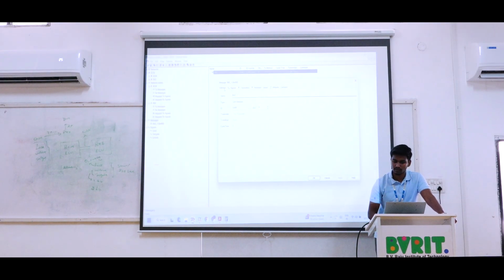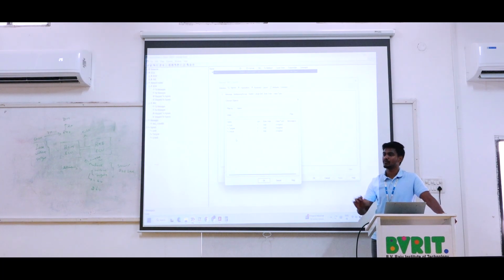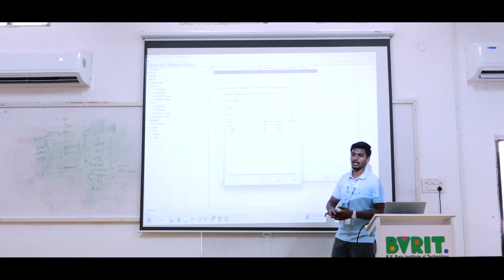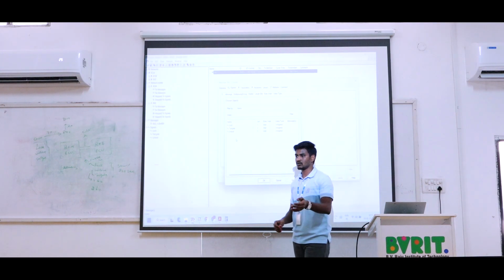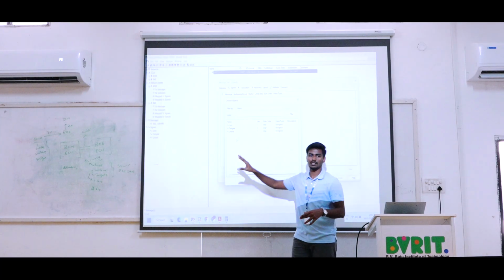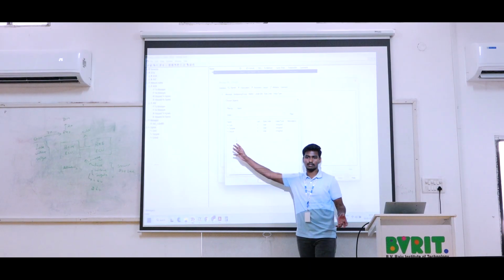Then go to the definitions of the RK1 and then go to signals. Here, from the top left to bottom, we have the add and remove options for signals. So we can give the add value, and these 3 signals we need to map to the ID number 400. The signal is not only for the particular message, because the ultrasonic sensor is used for the ADAS ECU and the RPAS ECU, and some monitoring purposes also. It will be taken for 3 ECUs, so we can use the signal values for any ECUs, there is not an issue.